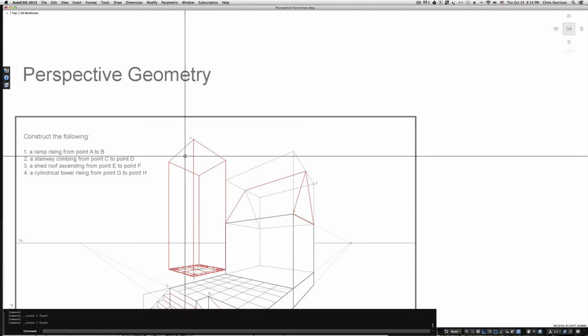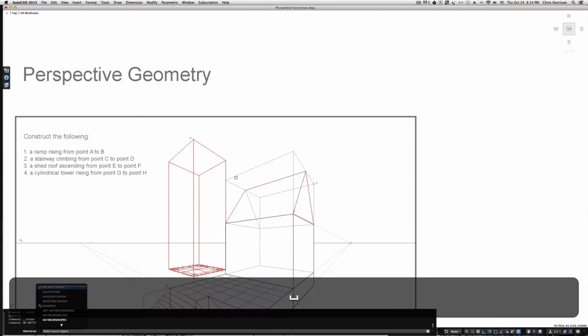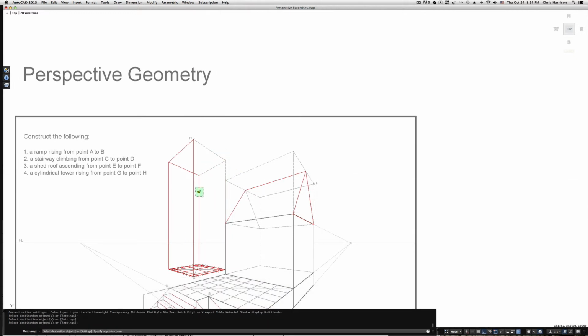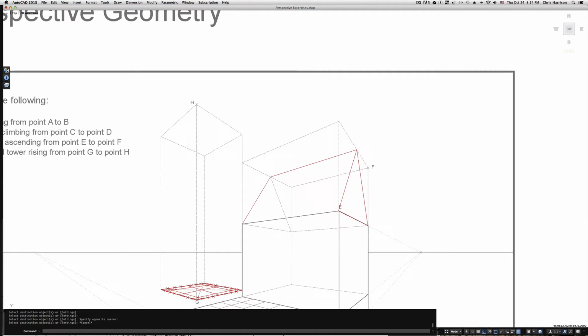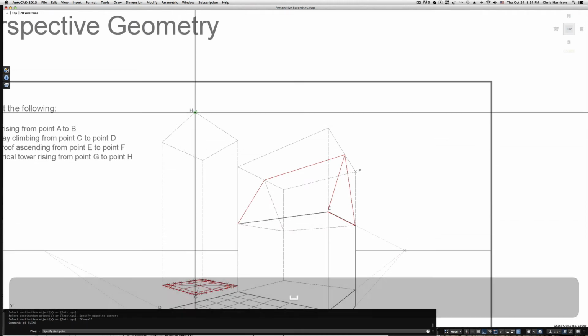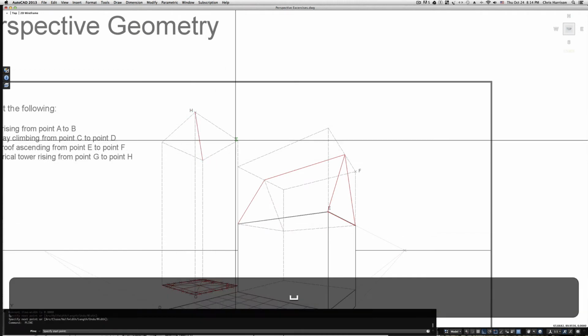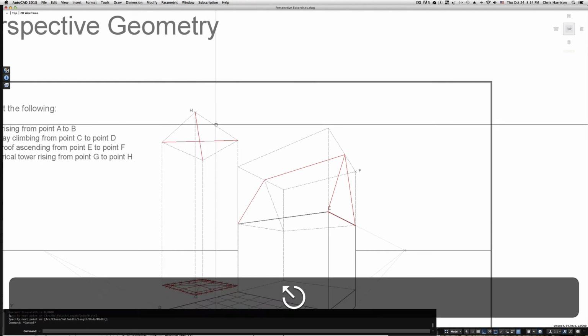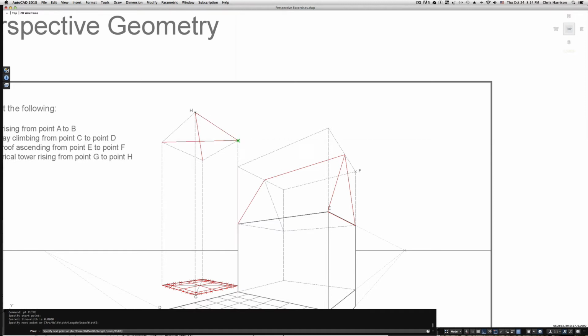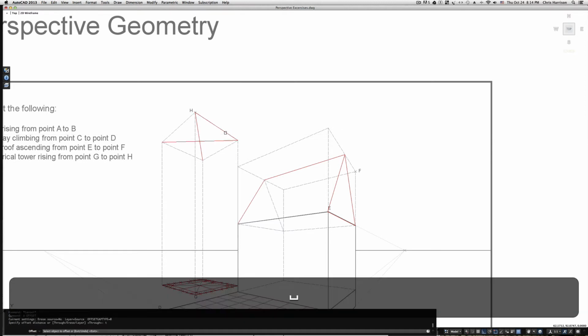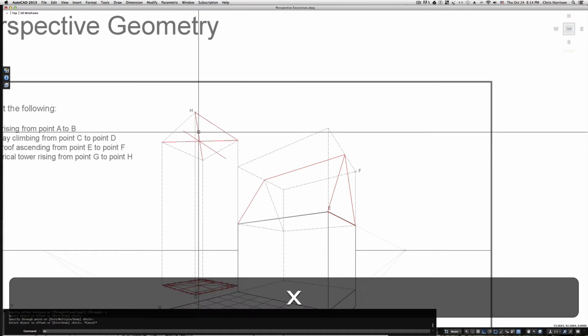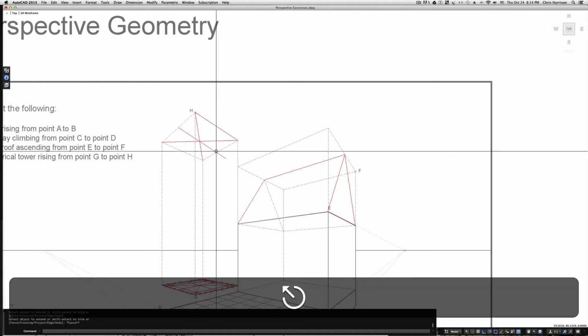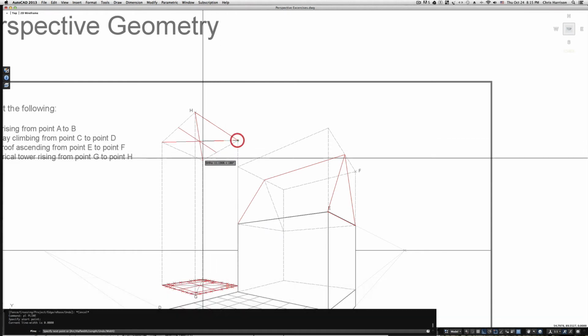I'm going to go ahead and make this a hatched line as well, because it's really just a reference for us. And again, I'll draw the diagonals in to define my geometric center. And do the same thing: I'm just going to draw a line in and then offset it to that geometric center. And just trim that out. Same thing this way.